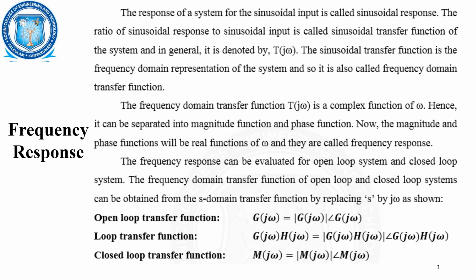So what type of analysis can be considered in frequency responses? We can consider two main functions in the frequency response analysis. One is the magnitude function, the other is the phase function. So we can consider the magnitude value of a term as well as the angular term. For example, instead of the Laplace transform parameter s, we are going to consider j omega. j itself is an imaginary term.